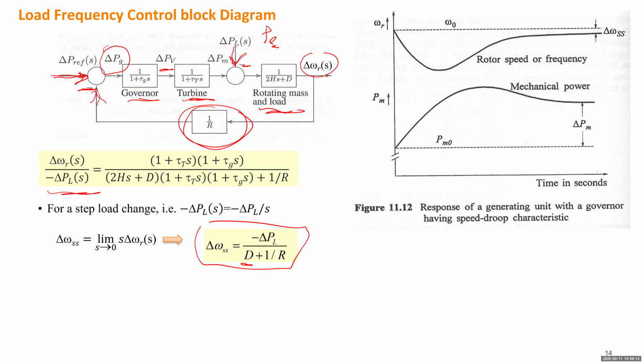This just shows the time response after a change on the load. First, you see the frequency will decline. It will follow a certain slope to decline. This slope depends on the inertia. Then the governor will try to recover the frequency back, and eventually there will be a steady state frequency deviation. And that frequency deviation cannot be 0 by using the governor. In order to bring that back to 0, we have to introduce another control.